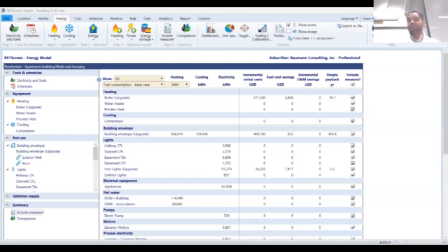That's a good question. And let's talk about DC, because this is a DC compliance requirement, right? It's $10 per square foot. DC has very strict guidelines on how they define gross floor area. For example, balconies are not gross floor area. EPA actually also has that. While I answer that question, can you pull up EPA's definition? Energy Star Portfolio Manager also has a definition of what gross floor area is. It does not include balconies, crawl spaces, or any exterior spaces.